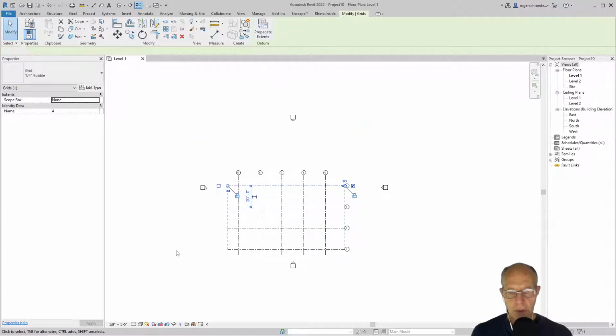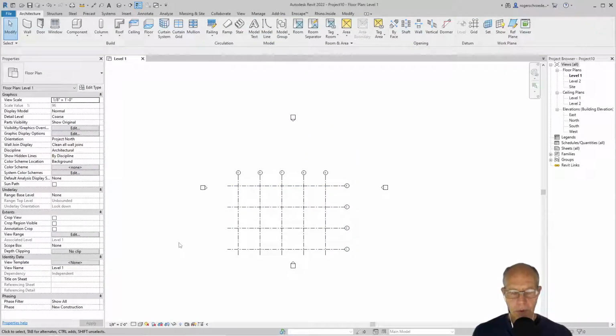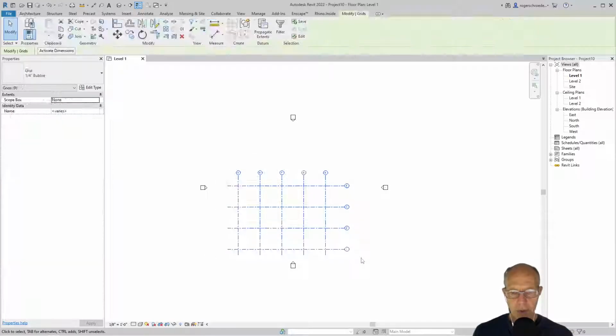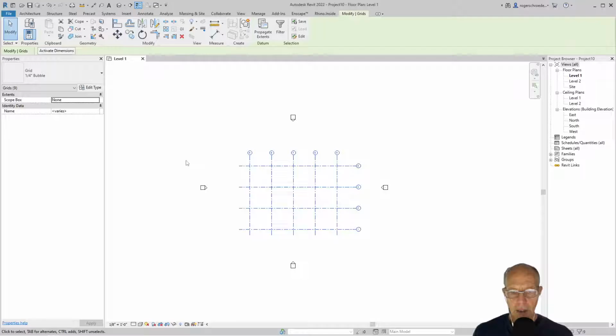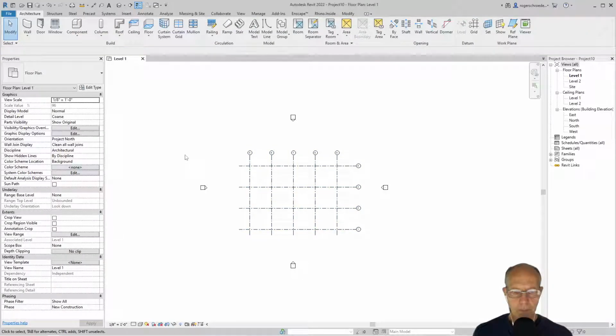And now you'll notice also that our grid isn't sitting exactly where it was shown in the first example I showed you. So one of the ways to correct that is to just draw a box over the whole thing. So I'm going to click and drag over the whole thing, select it, and then click anywhere where I grab an object and I can physically move it and kind of just eyeball it into position. So now we've constructed the floor plan or the plan grid view. The next we're going to look at is creating the elevation view levels for our project.